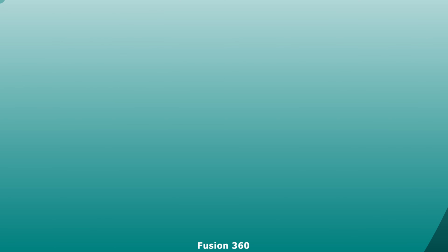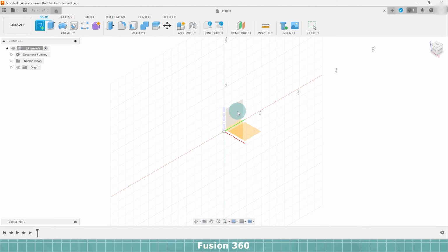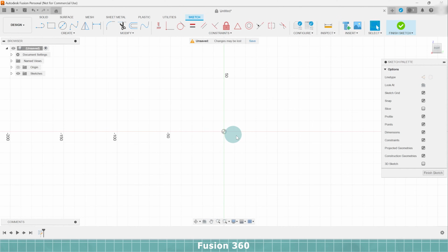Okay, now we're ready. We'll start off by first creating a 2D sketch, which is the foundation for building 3D models. When I click on Sketch, you'll see that the plane selections pop up. So I can select either the X, Y, or Z plane to begin sketching on, and depending on my model, I'll want to select the one that makes my workflow easy. For my particular model, I'd like to start off with the side view, then extrude from that. So I'll select the Z plane and begin my sketch.